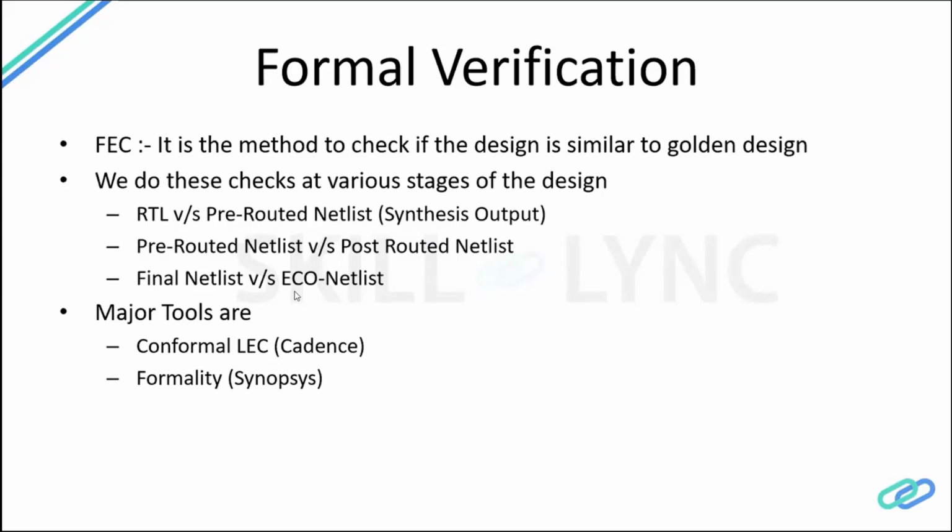How they do a fix is in the netlist itself. When we are doing the design, when we are creating a GDS, we add some extra cells in the whole design so that we can use those cells if there is some connection issue, or something got shorted. So what we do is we use those components, like AND gates, OR gates or flops, do the connections, and compare the final netlist with the ECO netlist. So that is called an ECO netlist.